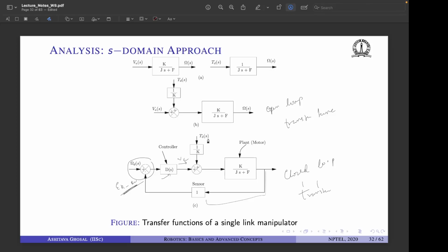And then external disturbances we are not controlling actively, they will come when they come, and the sum of both then goes to the plant, or the motor that we have, and finally we get the output rotation. Then we again take the actual output and feed it back to the desired, and like this the cycle goes on. So this is a closed loop controller, right?